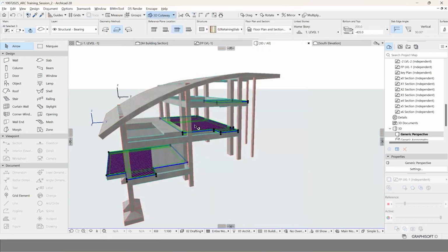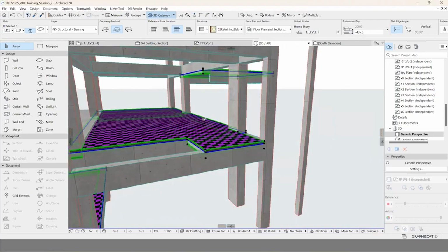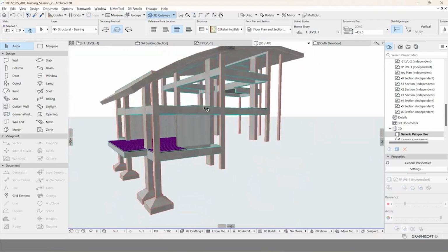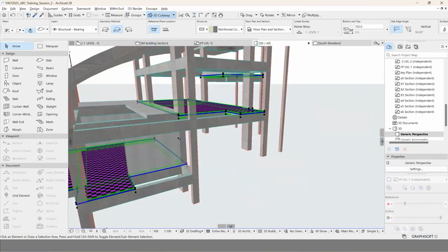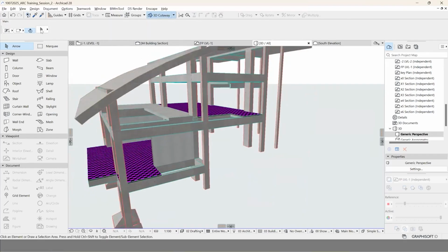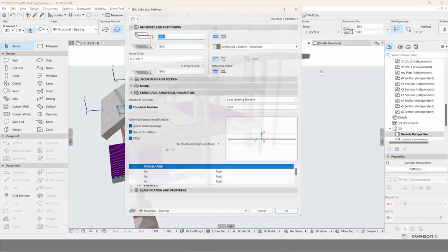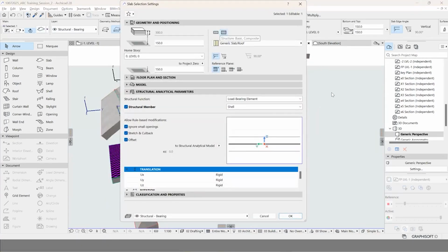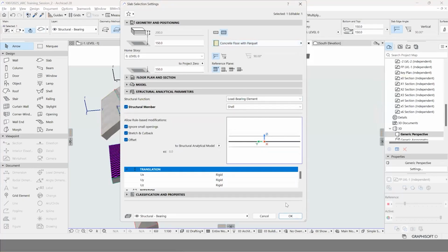Don't worry about this checkbox. This is because one of the properties is missing, which we will address by the end of the session, or when you're importing or merging a file, it will automatically be added. But yeah, that is one. And then we have one type here. Again, that also needs to be changed. So I go to the settings directly and do it. Change it to a composite. Go for this other type, top reference.